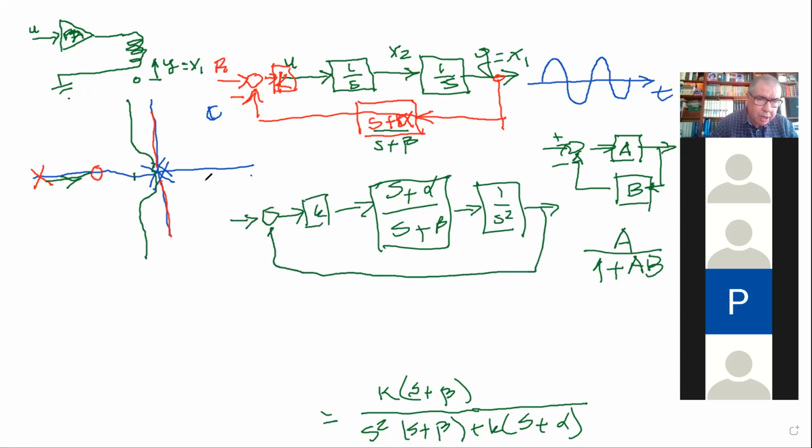This would also work, okay? At least the root locus would be the same. But remember that the root locus gives you the closed loop poles, not the zeros. And the zeros in these two cases are different. So you can stabilize the system either by placing a 0 here or by placing a 0 here. Is that okay? Okay, thank you.